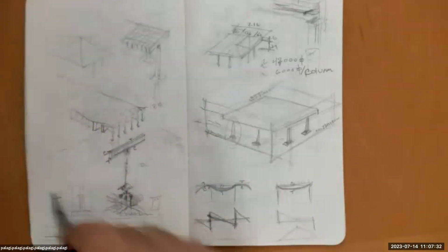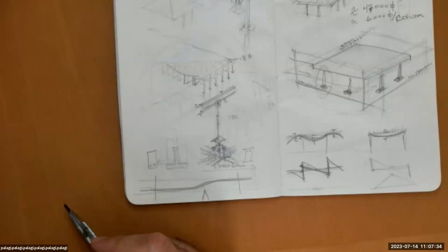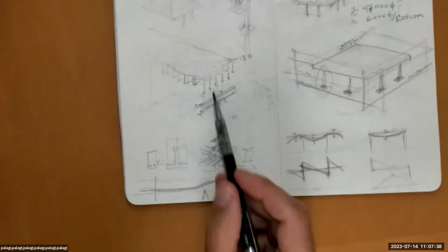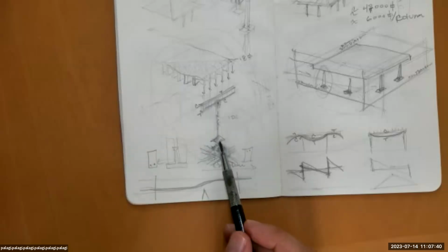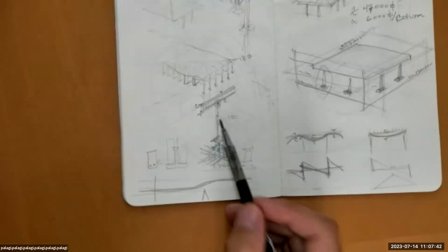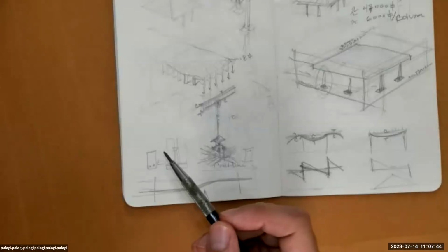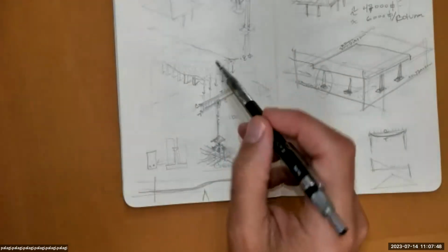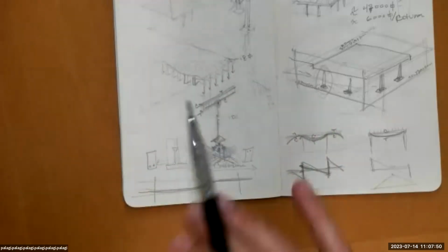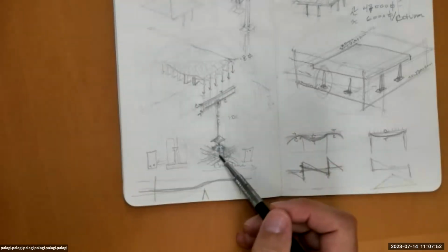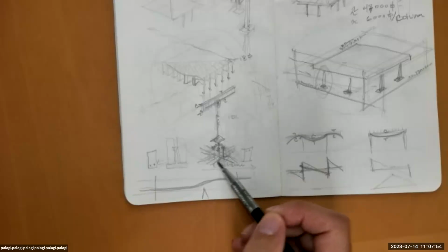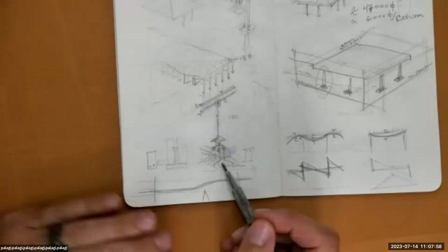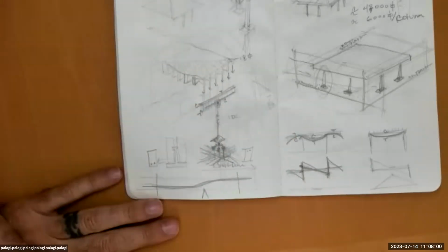So today, load path. In load path, we're usually looking at a specific element. So we're looking at, say, the load path of this, what falls on this column, right? We're selecting one column, and we're going to understand what all the vertical loads are. How does this building get to the ground? Now we're going to cheat and just take it down to this foundation, because there is a whole other concrete column below here, or a wall, as we saw in the under floor plan. But right now we're just going to look at this one.